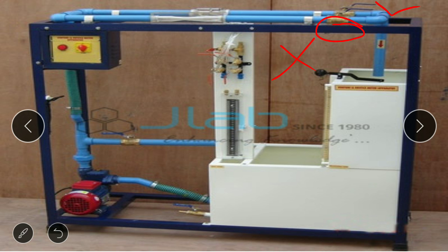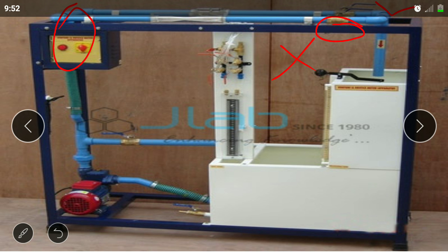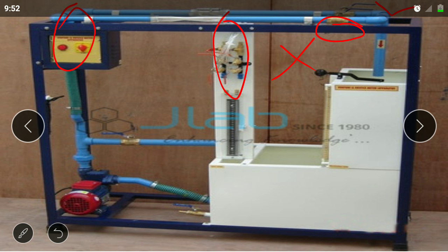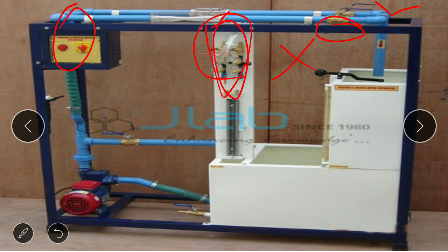And one more thing to be noted here, because we have to measure the pressure difference which has been created at this point and at this point, right? Vena contracta position. So we need a manometer, so that's why this manometer has been placed.